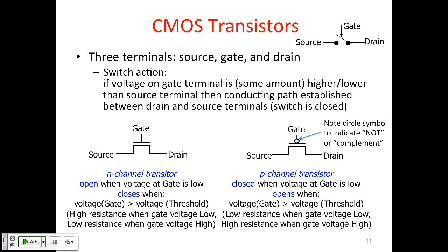All right. But the thing you have to remember: N-type, gate is 1, the thing is connected. If it's 0, they're disconnected. On a P-type, it's the opposite. Gate equals 1 means disconnected, and gate equals 0 means connected. But they're just switches. They're just electrically controlled switches.